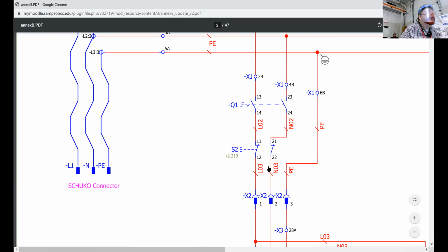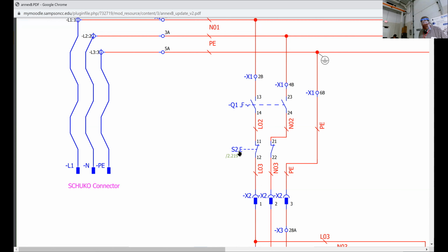Now, this device name, that's your e-stop. It has two normally closed contacts, and you see that little E symbol right there? That little E symbol is actually symbolic of a push button. So that's your IEC symbol. That's your giveaway for push button. So those two contact blocks with that little E thing there, you can say push button, and it's got two normally closed contacts.